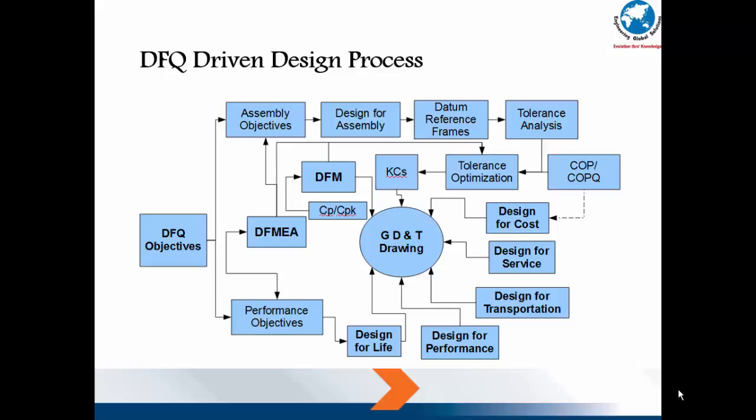The process emphasizes that interpreting a drawing, keeping in focus the quality objectives every step of the way, is possible at this time only using the GD&T approach. Plus or minus tolerancing drawings would simply not have the setup, the DRF or the datum reference frame, clear definition of the tolerance zones, and eventual compliance in inspection, leading to the whole process being ineffective. Simply put, GD&T forces design, manufacturing, and inspection teams to look at the product through the prism of quality.